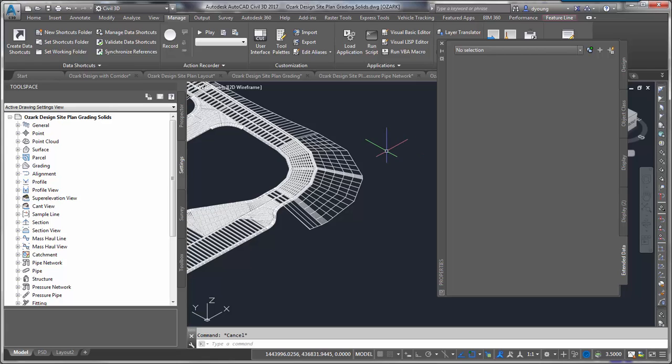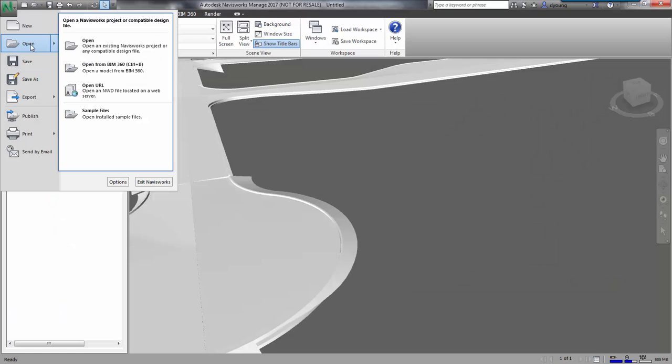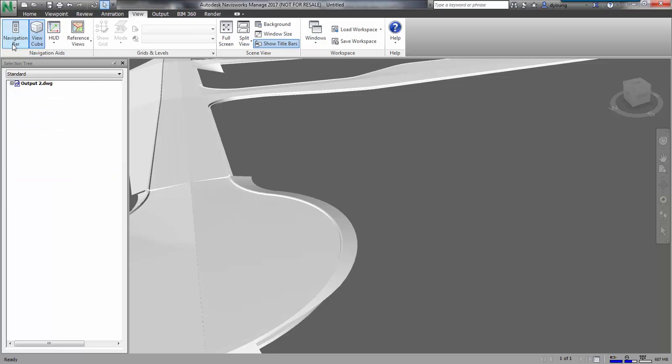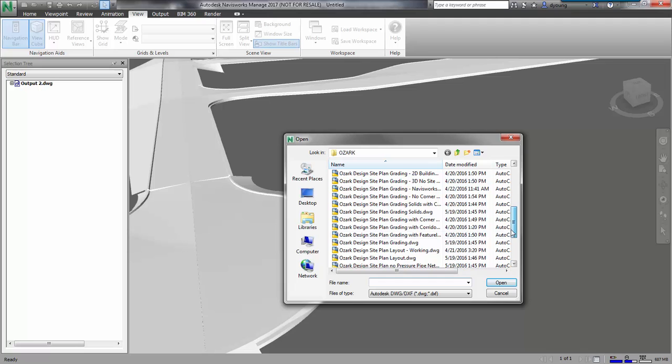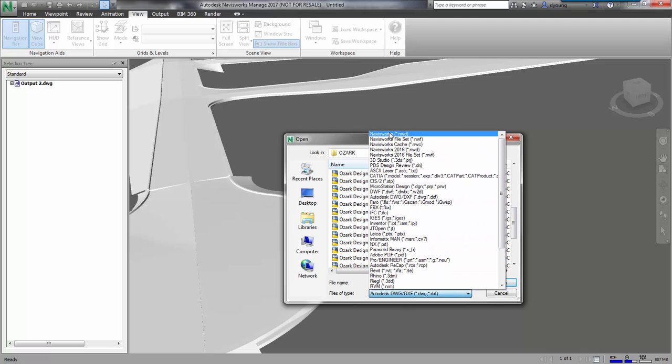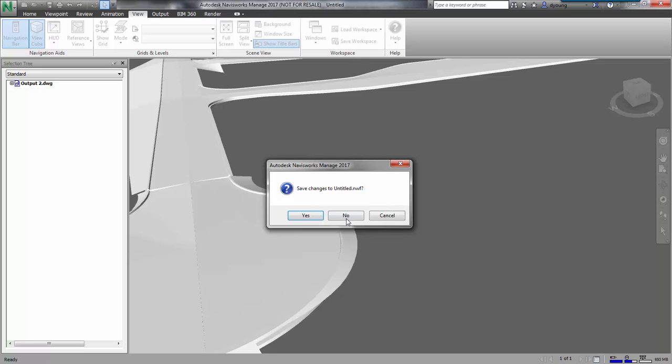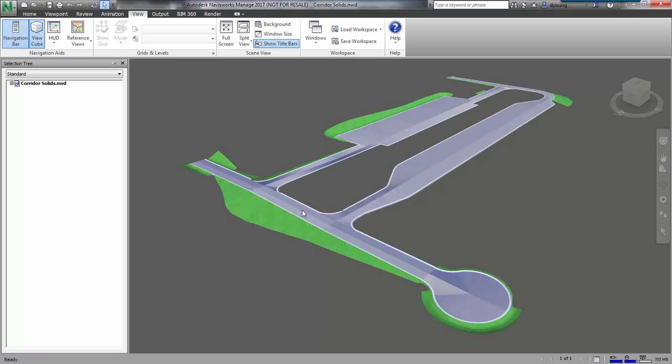So if I go back to Navisworks, I want to open up another one I've done. And the Navisworks model is already done. Now this one I've already applied materials to it, already created the tooltips for it, and now back in Navisworks, I can see that total cost field and the volume field and things like that showing up in here in Navisworks. So total cost is $88,439 at $450 per unit, and that data is now available coming straight out of my AutoCAD corridor.